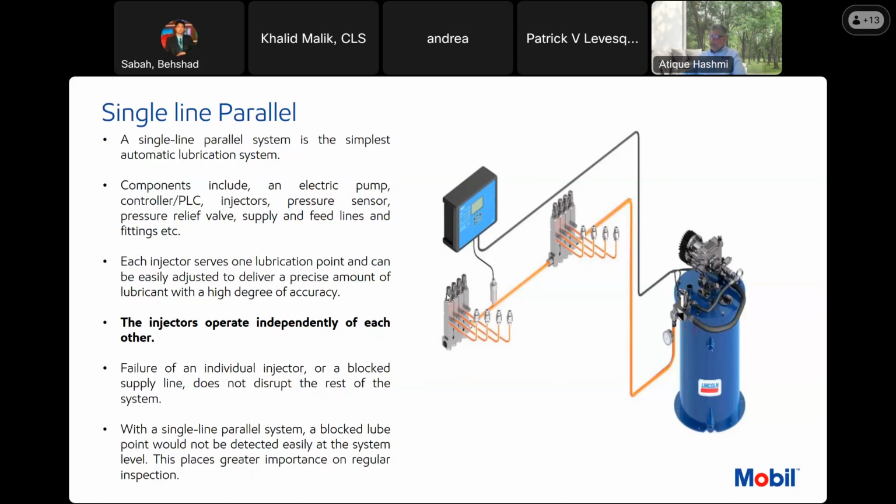So here you will see some screws. You can move them, you can open them to the maximum. Those screws can be set for the amount of grease to be dispensed from these injectors. So these can be adjusted precisely.